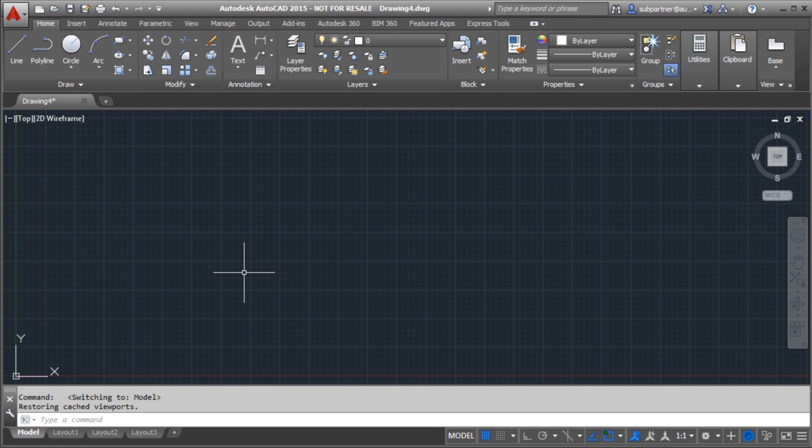So a nice way to understand how AutoCAD is broken down is you could think of its main sections. So it's tabs, ribbons, and panels. Now tabs would be home, insert, annotate, parametric. So these tabs are basically the main functions I want to do. And within each tab is a ribbon. And within those ribbons, it's broken down into panels that have all the tools I need to manage it, that is assigned to these functions.